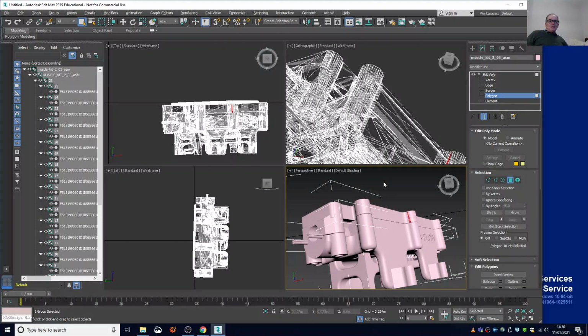Now one thing smart to do is, when you import your file into 3D Studio Max, make sure not to import the assembly, because then it becomes one object and it becomes tricky to open and unopen things. What's better to do is to bring in objects, sub-assembly parts, and then put them together in your scene. Okay, that's a better way of doing it. But again, I'm saying that, but it really depends on what model and what you want to do.